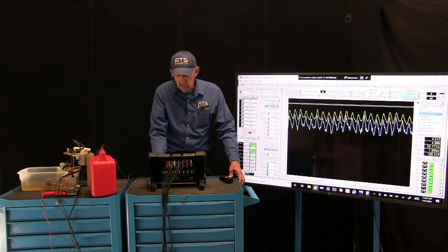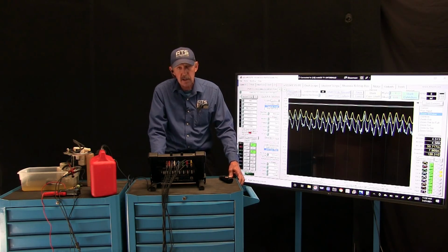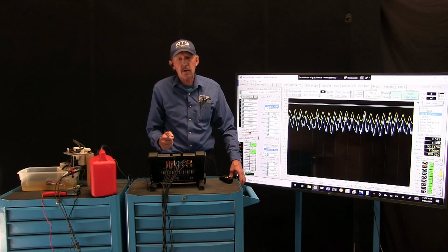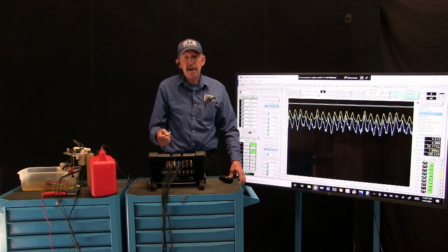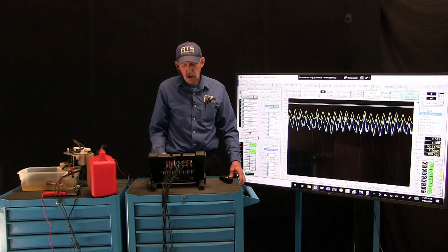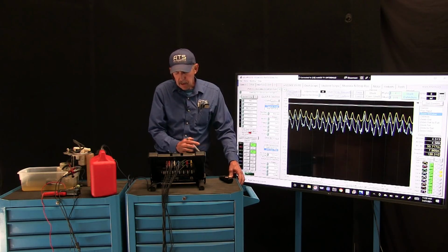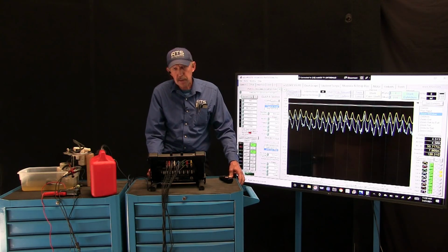So it's just another really great trick that I use a lot, because sometimes the current clamps are really hard to get down under the car on a circuit like this. And many times if you use a current clamp up on a fuse, the circuit can power other components, and so it gets you confused. If I'm always at the wire that powers the pump or grounds the pump, I'm always safer doing this kind of work. So now I can show you that the pump should have sped up.